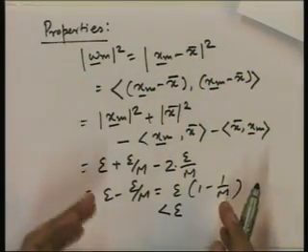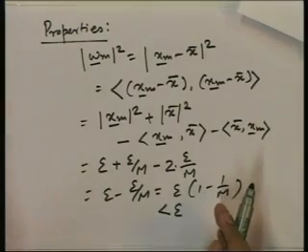So, the energy of each signal has reduced, but the distance between the points remains same, because all the points are translated by the same vector. So, the distance between them has not changed, and we have also discussed before that the probability of error does not change at all. So, we have seen that the energy of the simplex signal set is less than the original orthogonal signal set, though the probability of error for both signal sets is the same.